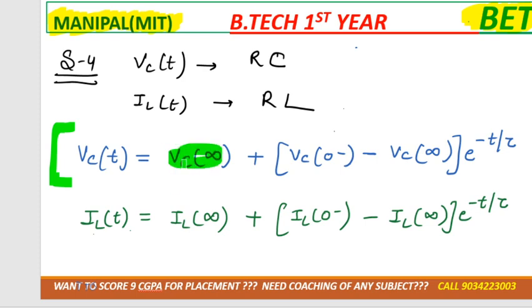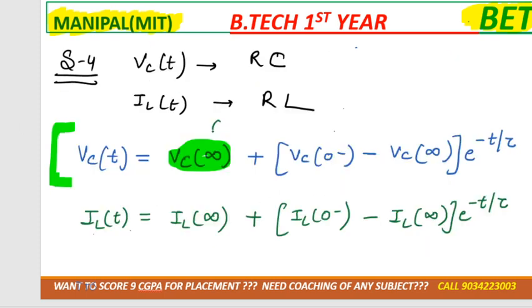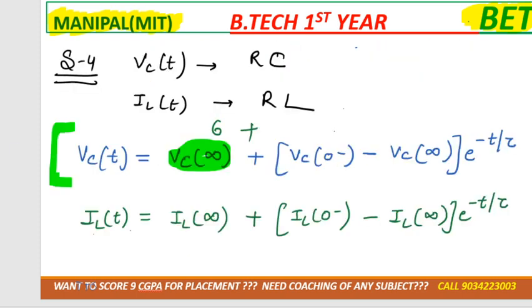Okay, VC of infinity we have already calculated. How much? 6 volt. Put it 6 volt. VC of 0 minus also we have already calculated, 0 volt. Put it 0 volt minus 6 again, and then e raised to power minus t by tau. Tau is how much? 0.11 second.